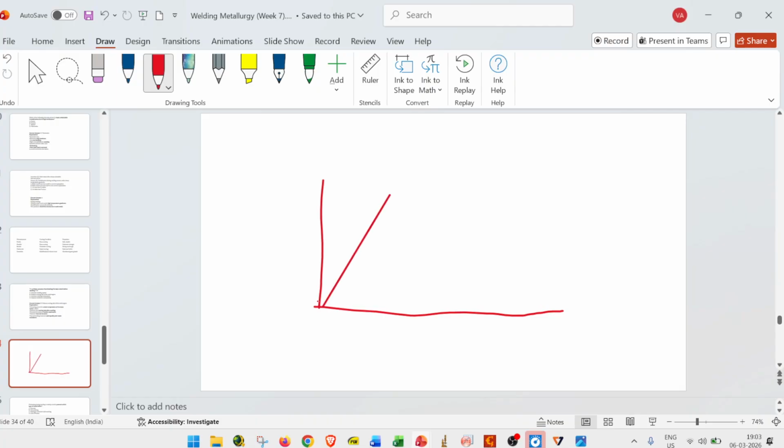The crucial factors for any heat treatment process: first is the heating rate, meaning the slope, how fast it heats up. Second is the temperature at which we hold it. So, what temperature we reach, at what rate, and after how much duration we hold it.